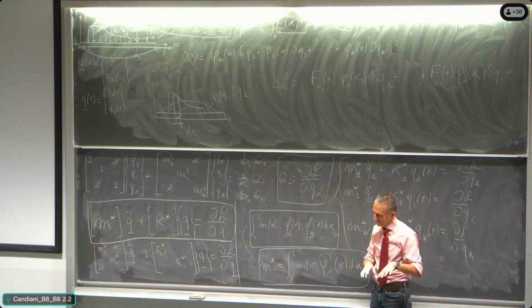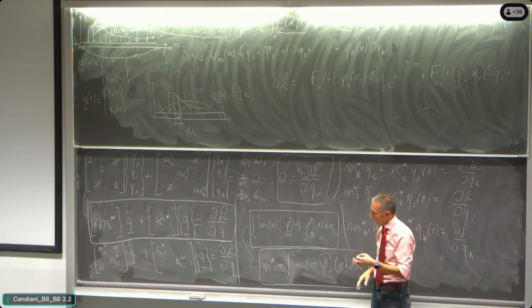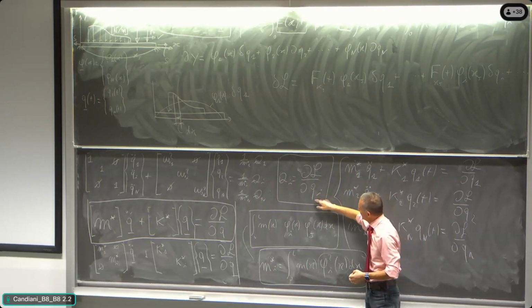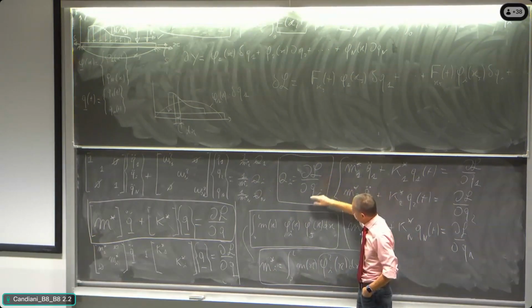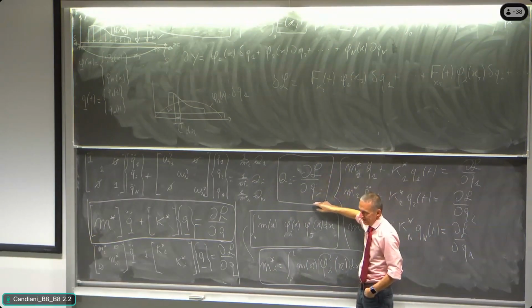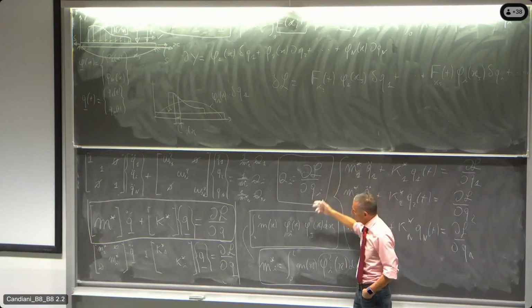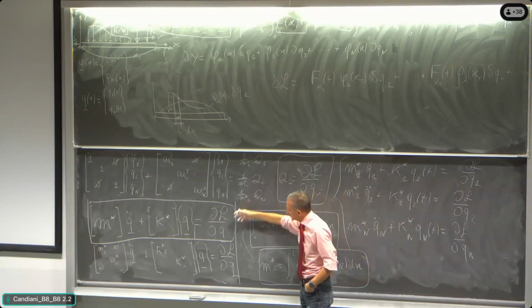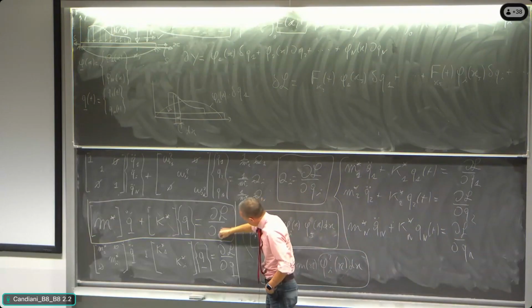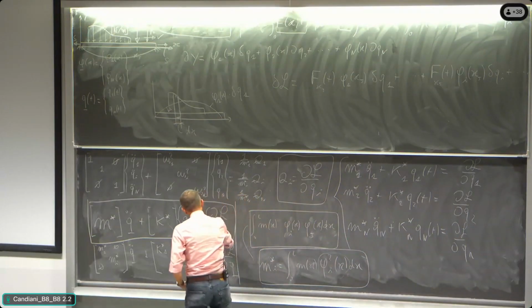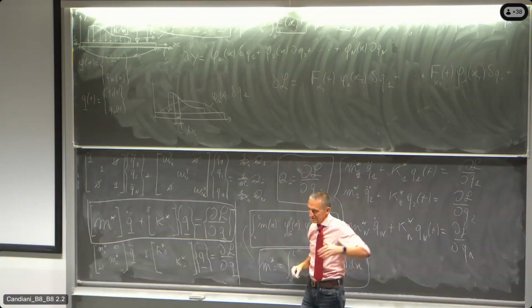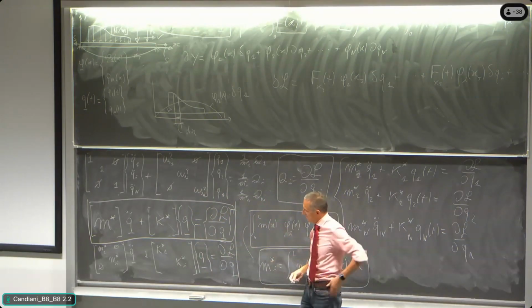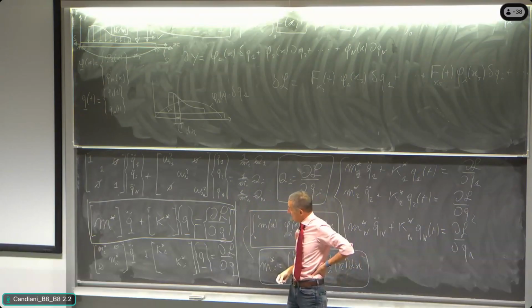Let's work with the operator. The operator is asking the derivative of the virtual work with respect to the vector q transposed. So here what was written is dL over dq vector transposed. What does it mean? It means the same story that we did for the matrix, for the mass, stiffness and whatever.